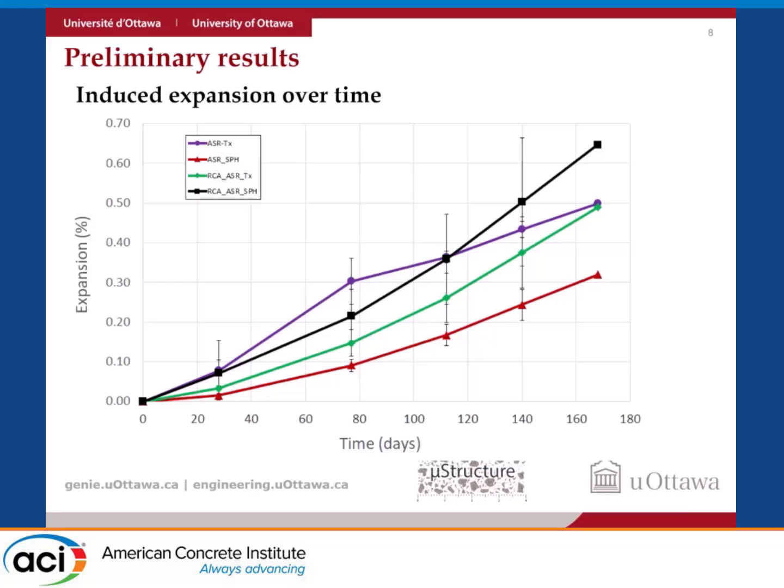But interestingly, if you look at the recycled concrete bearing a reactive aggregate as an original virgin aggregate, we have lots of room even to take over that expansion over time. So if the question, just in a qualitative fashion, was, can we keep having issues over time? The answer is yes. If you crush it and reuse it, there is still an issue going on. Plus, if you have your reactivity in the residual mortar, you can still have lots of further deterioration as well. So meaning that if you have any reactive material in a recycled material, this should be treated carefully, because you can indeed have secondary expansion.